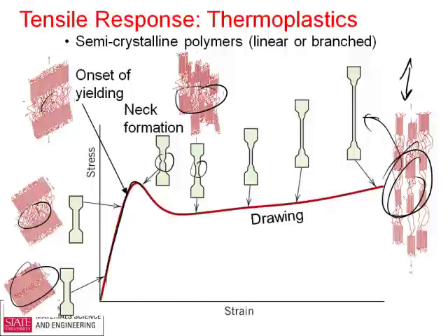Nature would rather see things random. So very often if you take this and heat it back up, you'll see it suck back close to its original shape, not exactly. And that's one of the experiments we often do in these materials camps, to show the shrinky dink effect, where if we heat a polymer, we can cause it to change its shape, go back to this high entropy shape that is low energy that it really likes. This is a kind of experiment you can do very easily with a milk jug, or even these things that are used to hold 6-packs together. That's also polyethylene. You can cut out a little piece of that, and if you pull on it, you can even do this by hand.